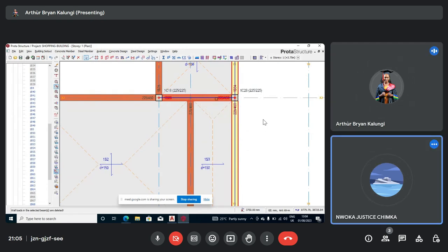just know that in a case where you don't know what to do, you can leave it like that. It is good for you to design for a worst condition, and the worst condition for that beam is for the whole beam to carry wall load, right?